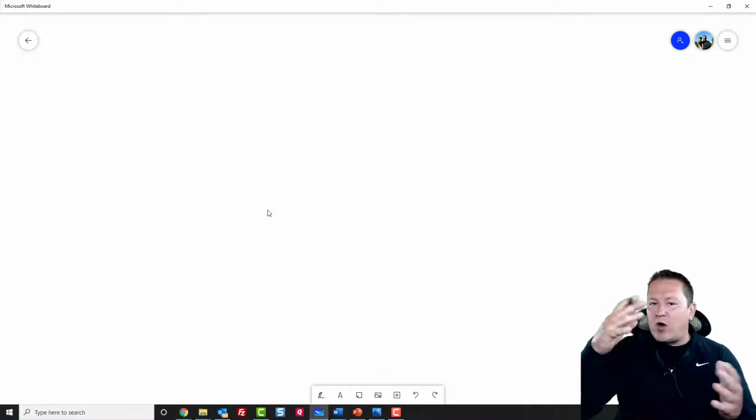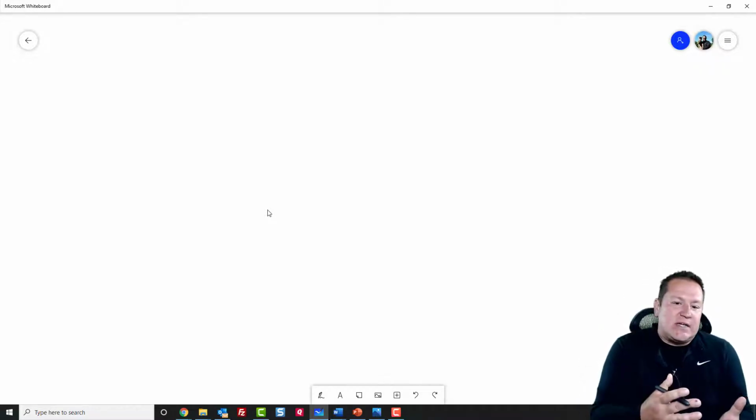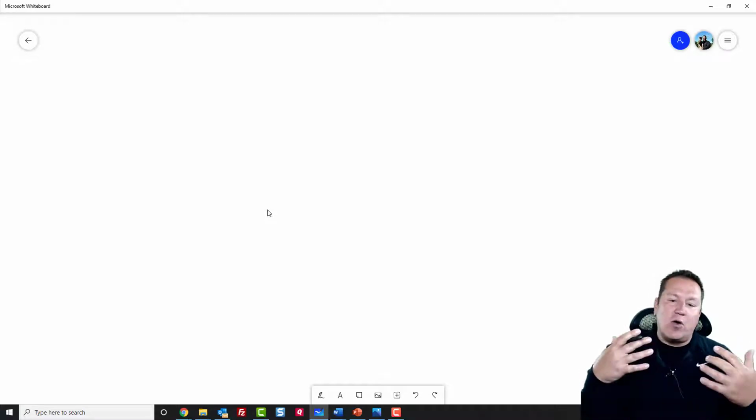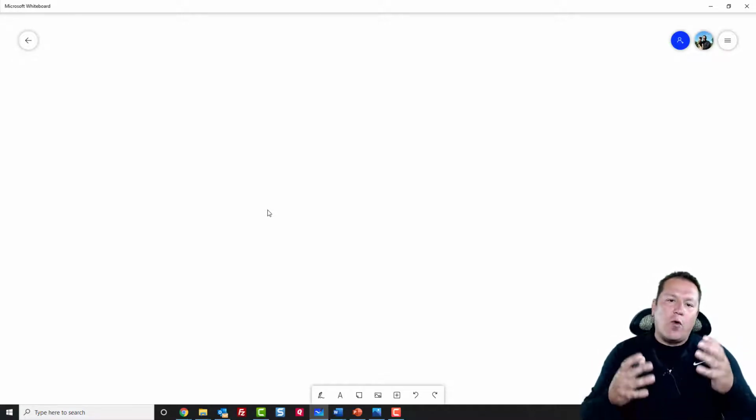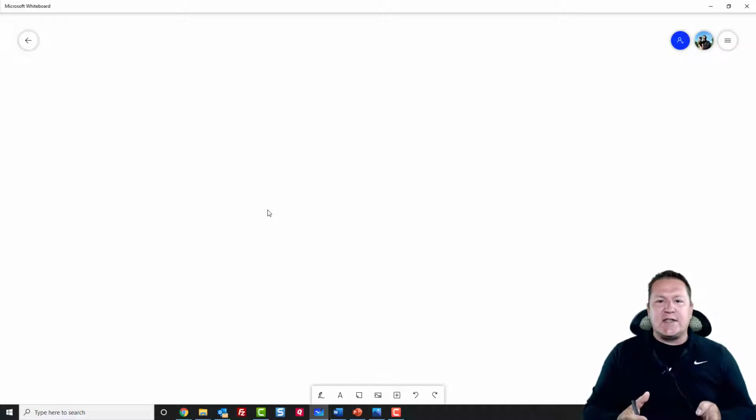And we have all these tables. In the CEC, I'm from Canada, so you have your tables 1 through 4 that give us all the different conductor sizes in one column, and then depending on the temperature of the conductor's insulation, the different ampacities or current carrying capacity of that conductor. But where are these tables really derived from?